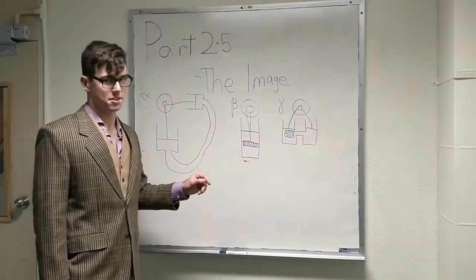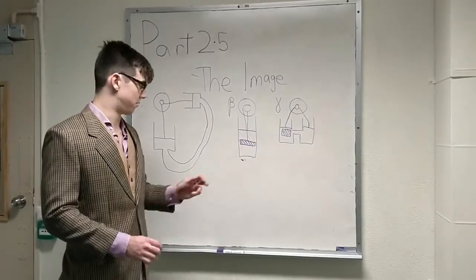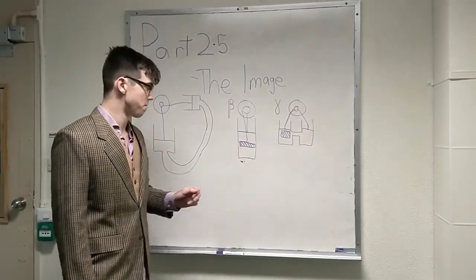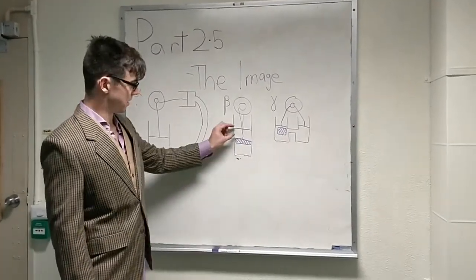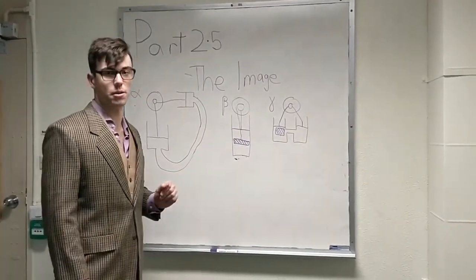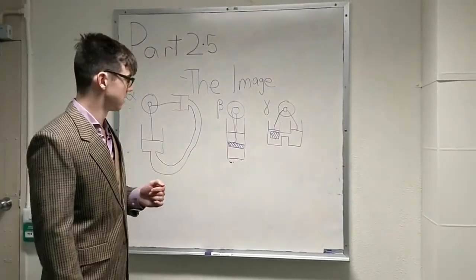The beta Stirling engine has two pistons, however one does not seal all the way to the edges, which allows hot air from the bottom, where it's heated, to pass up and into the middle chamber, which is where the cold air is, which is then compressed and expanded by both the pistons.